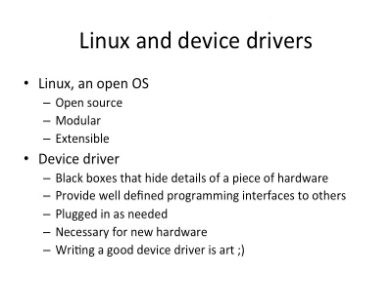For example, what if you can provide them a file, and the name of this file could be /dev/parallel ADC, and the way to interact with your device is to read and write to the file, and the user of your sensor will be happy because he or she does not have to learn all the low-level details. But in order to provide such an interface, this special file, you need a device driver.